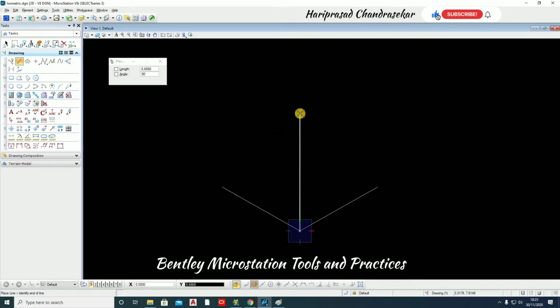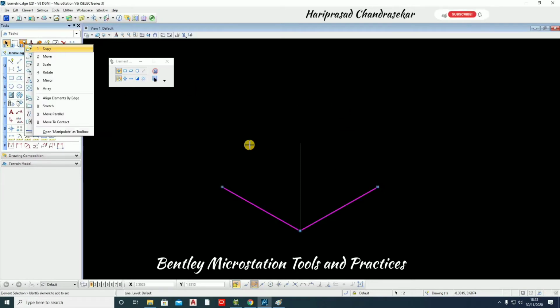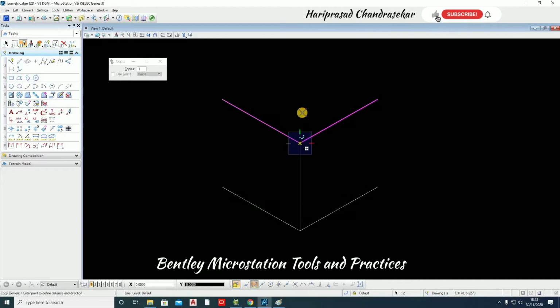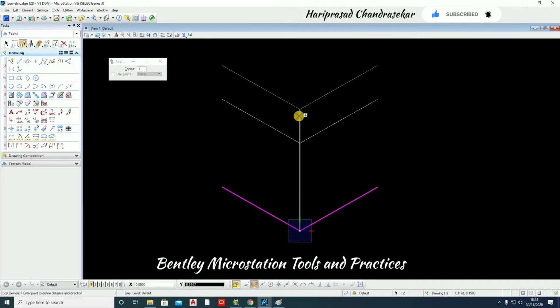And here you can directly put it. Okay, and you can just copy it and then place it. I'm just selecting this and going for copy from here to here. Escape 1. So whenever you want to escape, you need to click escape 1. To copy together, you just hold control, okay, and then you select both, and then just click copy. And then you just put the base point and then the destination point.